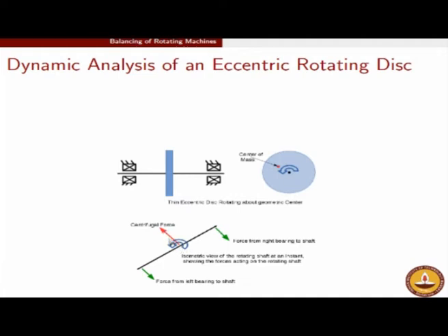But now this rotor is subjected to a centrifugal force, and to balance this rotor shaft system, the bearing must put in these forces. So the arrows indicated by green on the left and right end of the shaft indicate the force which the bearing puts into the rotor shaft system, such that the rotor shaft system can remain in equilibrium. So these two forces supposedly balance the centrifugal force, right?